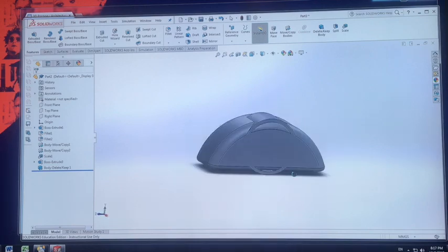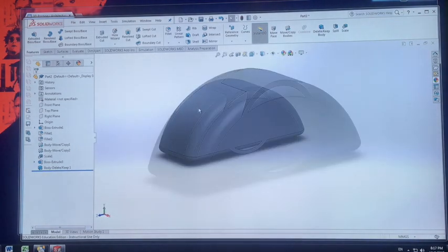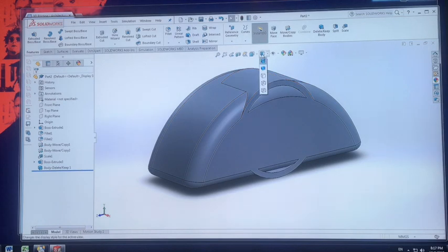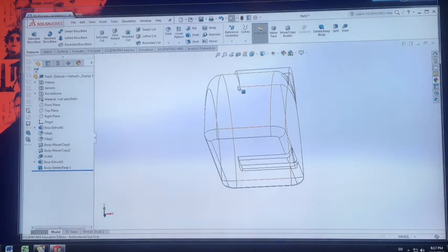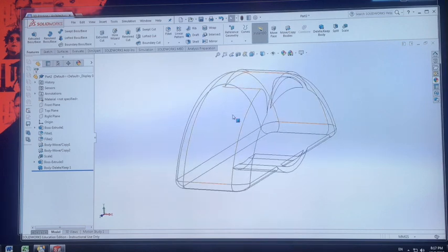All right. If you want to check, do a quick SolidWorks check of that body and the design. Just have a quick look with a wireframe just to see that there's no accidental gaps on the inside or errors or surfaces that look a bit weird. You may want to try and fill those in or remove those before you go to that next step of exporting.